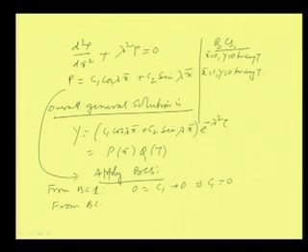And from boundary condition 2 we have 0 again equal to C1 cos λ plus C2 sin λ, for x̄ equal to 1. The first part is 0, since C1 is already 0. So we have got 0 plus C2 sin λ.